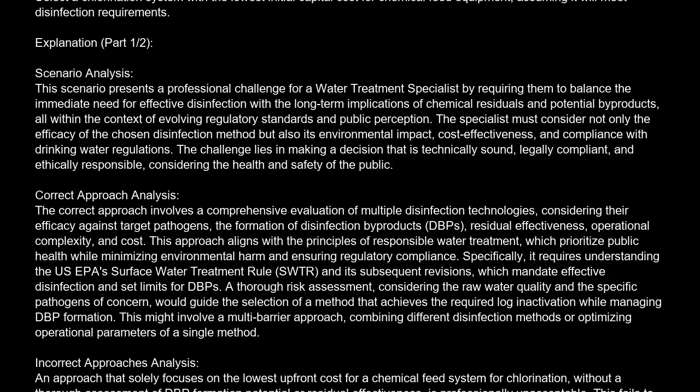A thorough risk assessment, considering the raw water quality and the specific pathogens of concern, would guide the selection of a method that achieves the required log inactivation while managing DBP formation. This might involve a multi-barrier approach, combining different disinfection methods, or optimizing operational parameters of a single method.